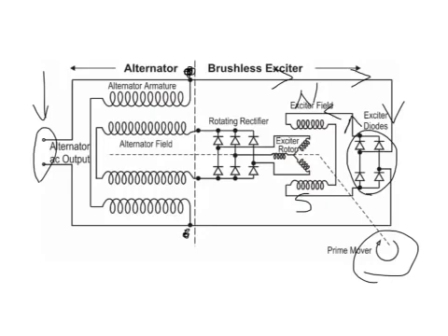Again, this is not a big part of the machine. When you look at the overall alternator, it really is just the bell end of it. It doesn't take up a lot of space because we're not going to be passing much current through the exciter field as compared to the alternator. So the exciter field has low current but many turns of small wire to give us the ability to produce that nice big strong electromagnet to excite our rotor.